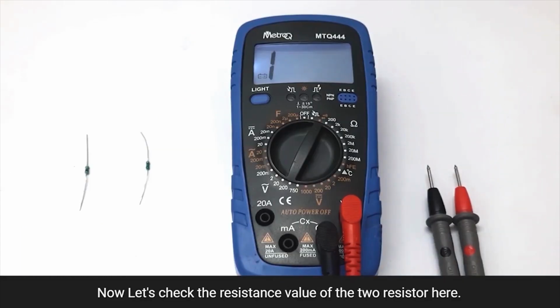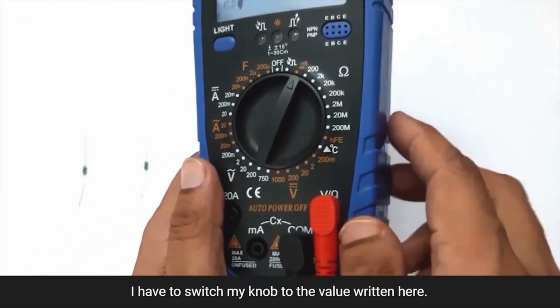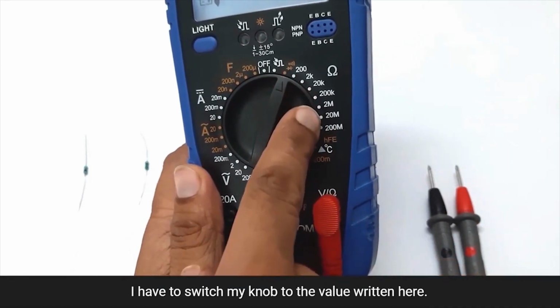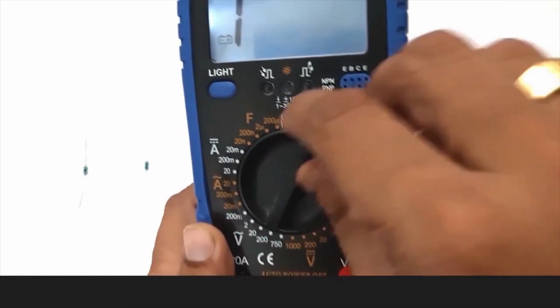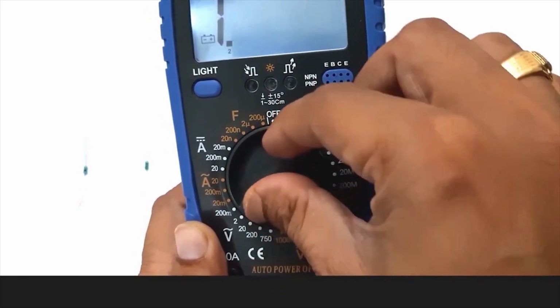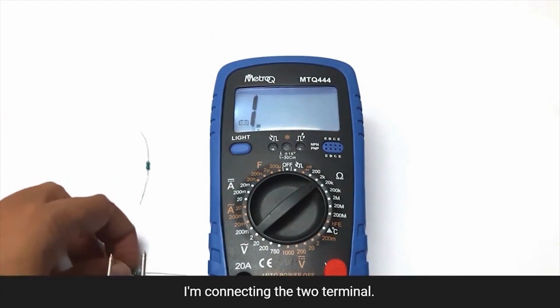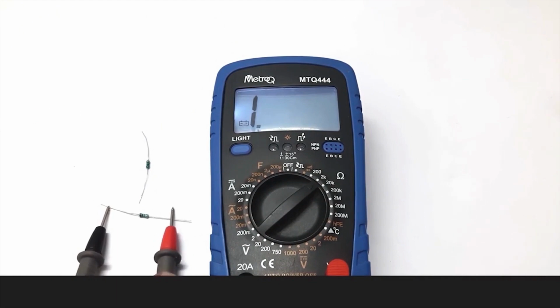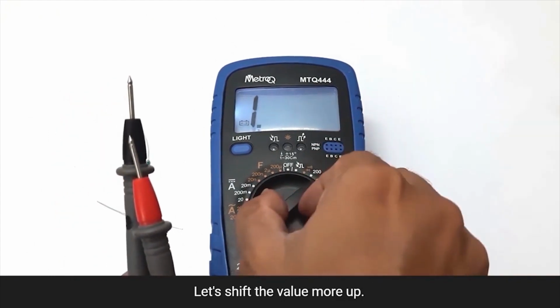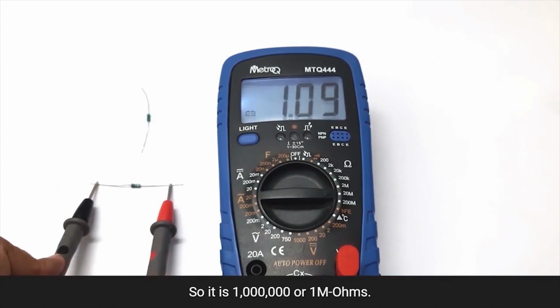Now let's check the resistance value of the two resistors here. To check the resistance value, I have to switch my knob to the value written here. You may see there are multiple values written here. You have to find the exact range of the resistance. I'm switching it to 2K. Now let's check the resistance. I'm connecting the two probes to the two terminals of this. It's not showing anything. Let's shift the value more up. So it is 1 million ohms.